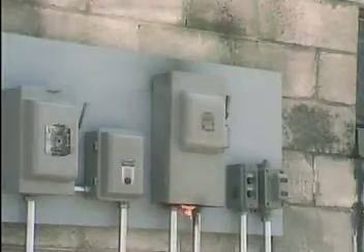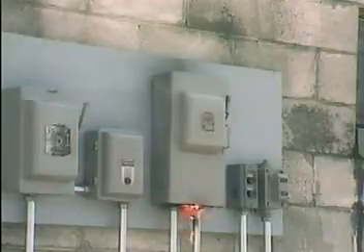Another hazard that you may have to deal with is an electrical fire. Electrical fires can happen for many reasons, and it may be part of your job to respond to them. Generally, the first thing to do is report the fire. Reporting the fire will set in motion other emergency actions, such as isolating circuits to prevent injury and equipment damage. Then try to cut off power if possible. This takes away the source of ignition.